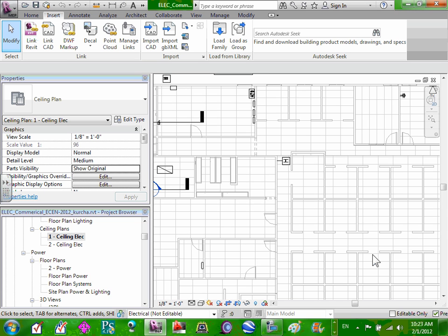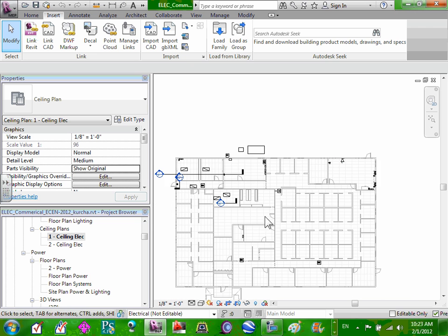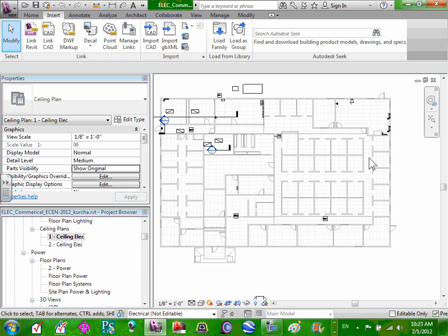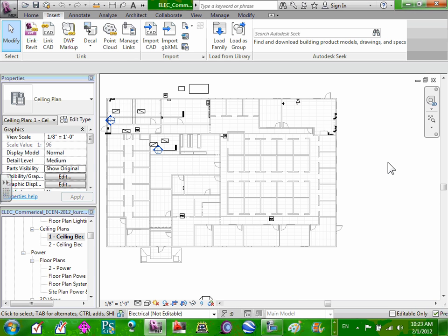Look at it from the standpoint of trying to get out of that building with no lights when you're laying them out. You need a path of egress. And you should be able to see an exit sign wherever you're standing in that building, to see the closest exit. Not in private offices, but you should be able to walk out into a common space and see an exit sign.